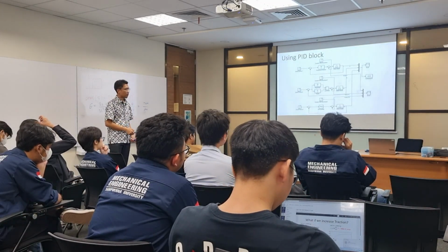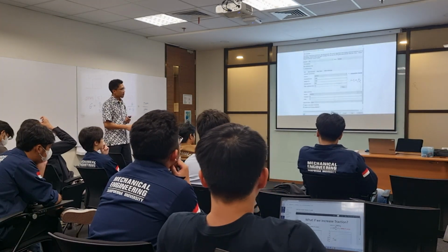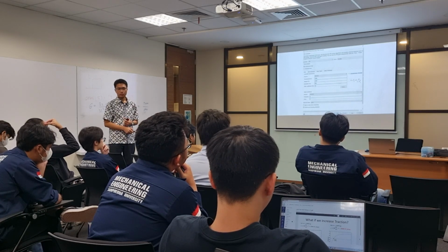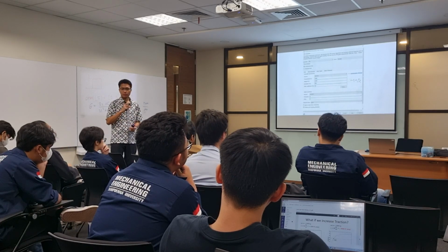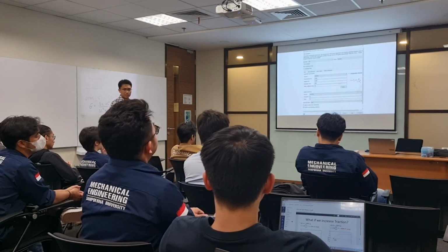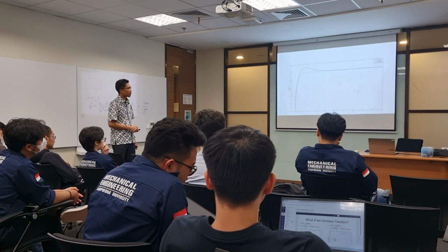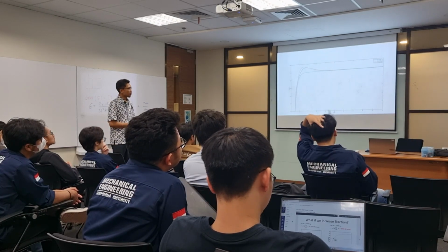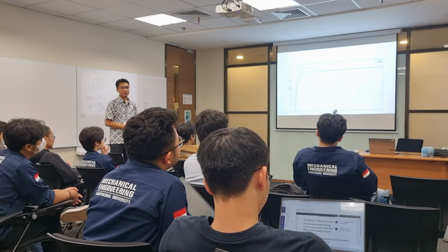Let us see how they perform. Of course, there is an automatic tuning available in here. If you don't know how to tune it, you can press tune, and then MATLAB will compute the correct P, I, and D constants for you. Okay, and this is the result. For the PID controller, we can slightly reduce the overshoot, and then the steady state error is still zero.